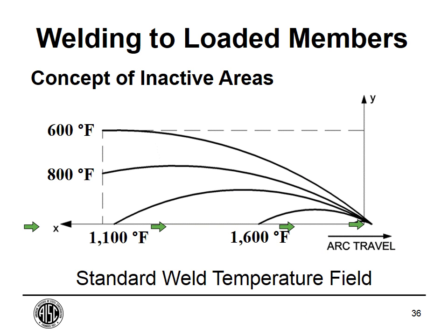And what we have plotted is the temperature field in that plate. And you can see what happens. If you move away in the Y direction, perpendicular to the weld up here, that is roughly, for this heat input that this was plotted at, roughly 1½ inches. And it's to scale, so this dimension in the X direction may be 5 or 6 inches over here. So what we end up with is the different temperature lines, 600 degrees, 800, 1100, and then 1600 degrees Fahrenheit is what these temperature lines are.